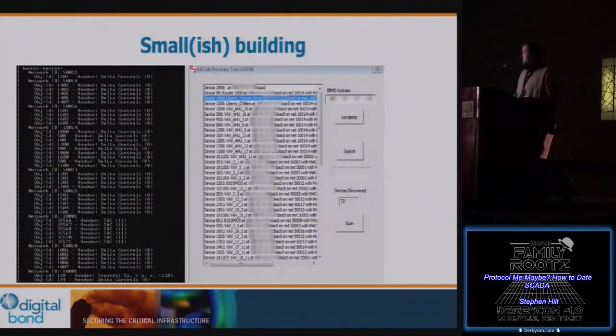the script on your left is a script that we wrote, because some devices never delete you out of their table, based off our testing. That's one we don't release, but you can do the same based on information in a BACnet browser.